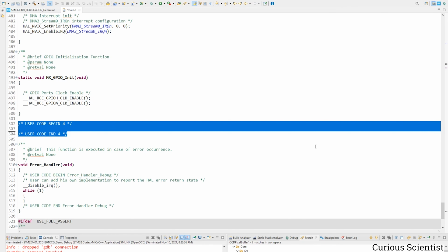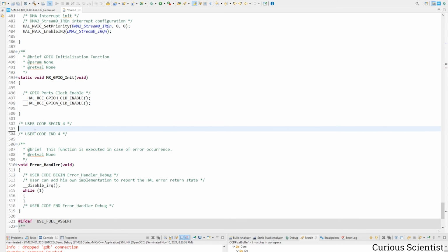So now here we have to use our own code, and in this place we have to use the function of the ADC, which is called when the ADC conversion is done, and that is the HAL ADC conversion completed callback function. So once we measured our pixels, we have the pixels in the DMA, and then we want to dump that bunch of pixels on our USB.